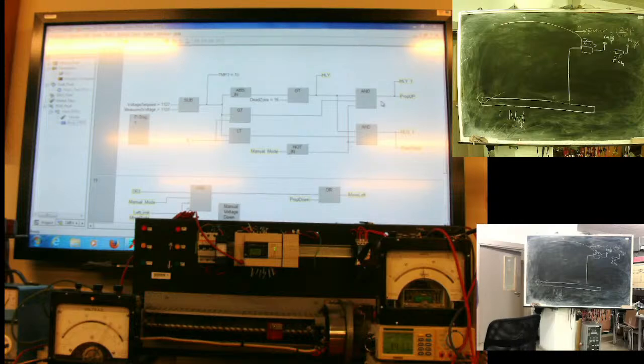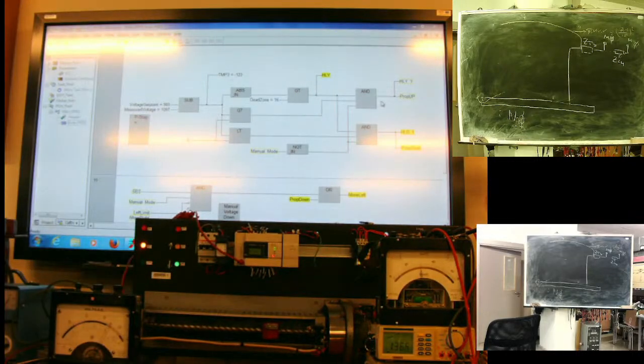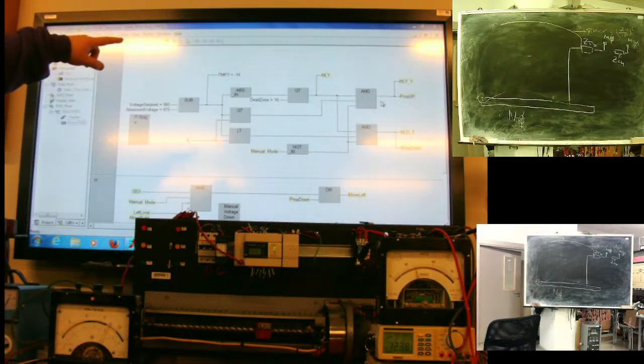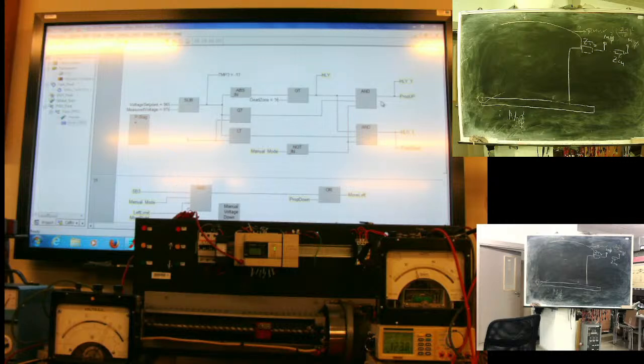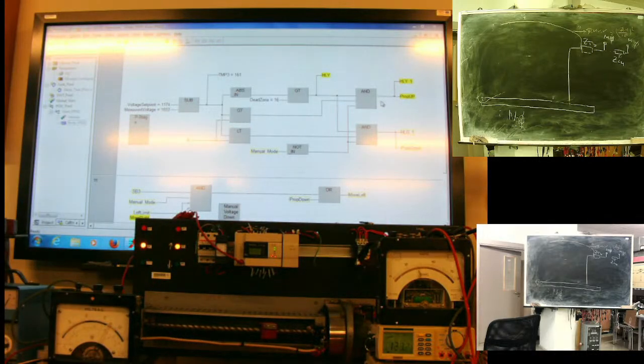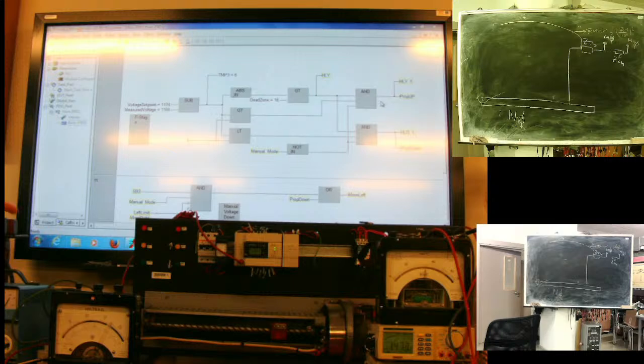What's going on inside? It has 2 channels. One is voltage set point. I can change it. And another is a measured voltage. And this logic tries to keep them equal. It changes, you can increase. Goes, measure it until they're equal. It's one moment because I cannot set voltage absolutely precise. Winding has a step. So that zone of 16 relative units is introduced here.